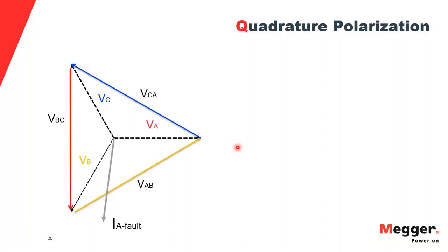So this is a very good design used in many of the directional relays, where they basically sense the other phases for voltage and keep that as a reference. Now, why do we call that quadrature? Quadrature is nothing but 1 by 4, right? So in the reference plane, you have 360 degrees multiplied by 1 by 4. So you have 90 degrees. So this is nothing but a 90-degree connection, right?